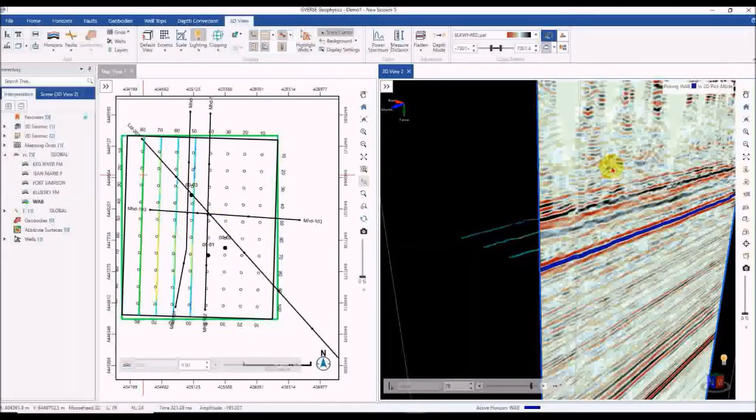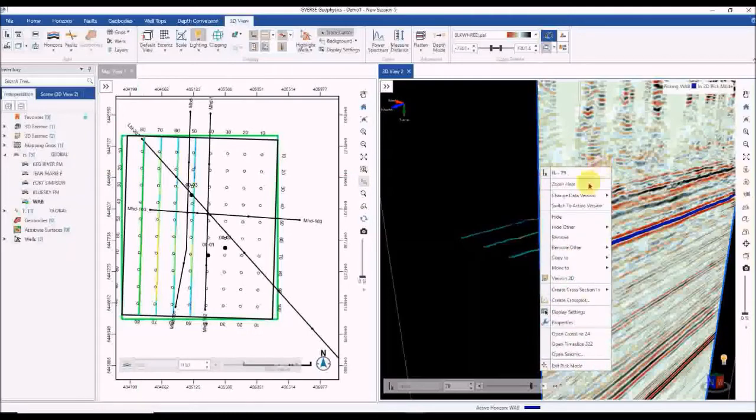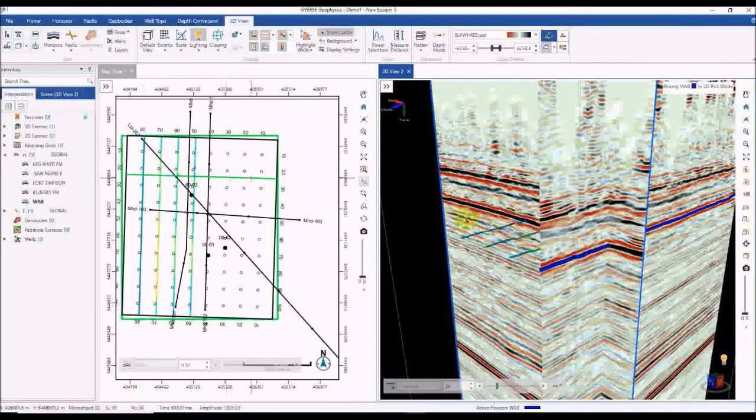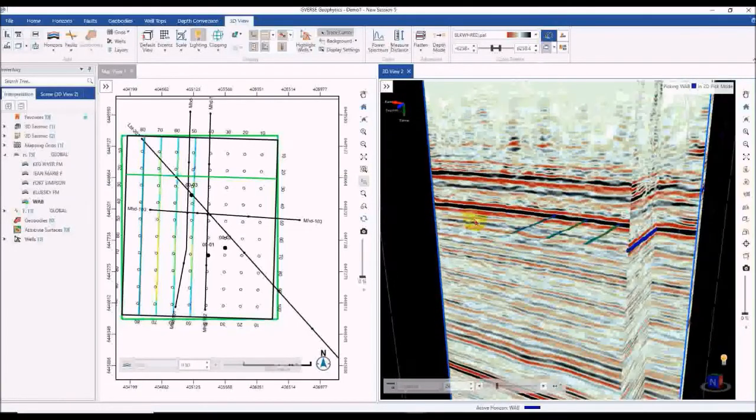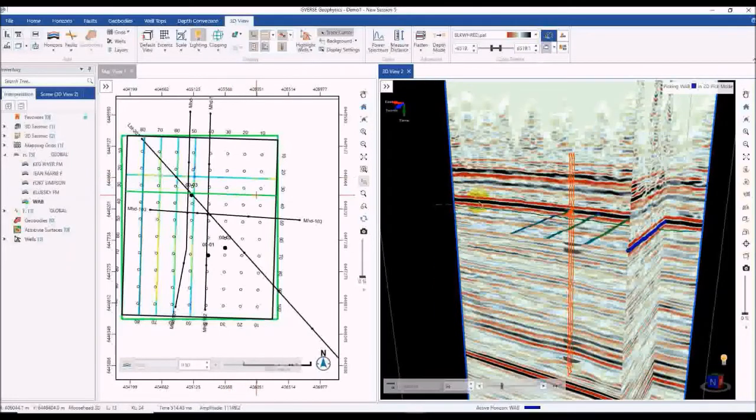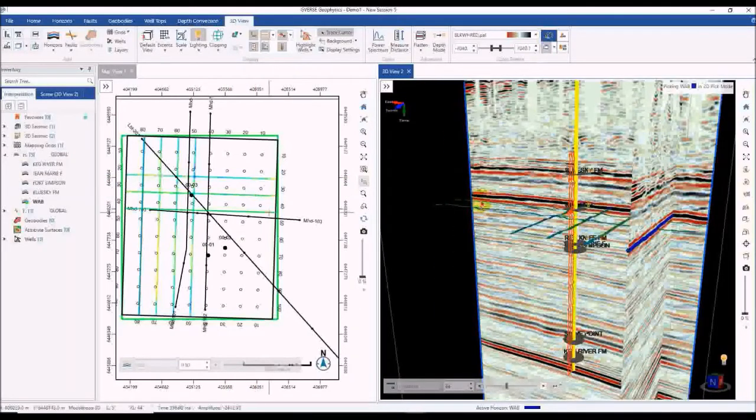We could also right click in our seismic line and change directions, and we have the ability to see the horizon that we're picking in the other orientation. So in this case, we have noticed that this is an intersection. We could click here, and you notice how it's been performing this line. We could also, as we have changed the inline, go back and continue either with the arrow on our keyboard or by clicking this tool option right here.